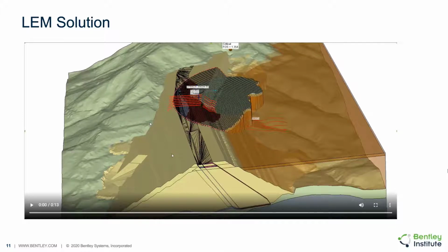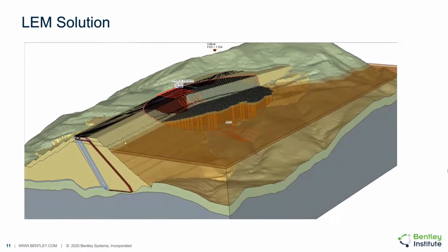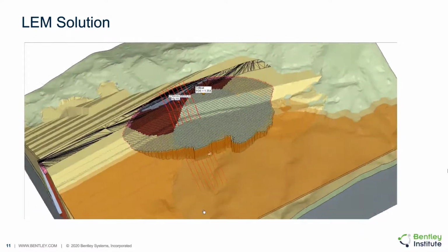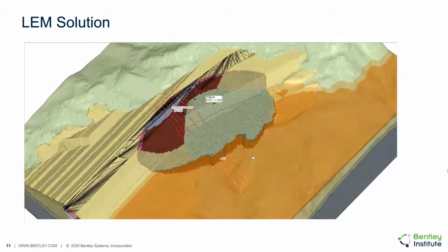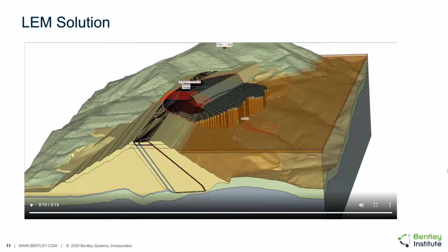This animation shows the completed analysis utilizing material volume meshes in order to represent the complex combination of central and upstream alignment of the dam core. The spatial analysis feature allows the stability to be analyzed at a number of different locations across the earth dam structure in 3 dimensions. The resulting critical slip surface geometry can be seen. The color of the columns relates to the material that is sheared through at the base of each column. Therefore, it can be seen that the material sheared through represents a very irregular and 3D pattern.